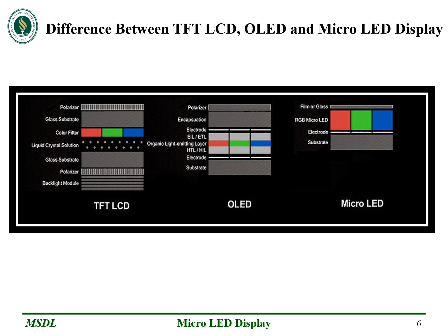TFT is a thin film transistor liquid crystal display, the technology to improve image quality such as contrast. In a TFT LCD, the setup of an electric circuit at the liquid crystal layer would trigger the transfer of the molecule layer, which, coupled with the color filters and backlight source, endows each pixel with three original colors, red, blue, and green, whose mixture creates light in various colors.